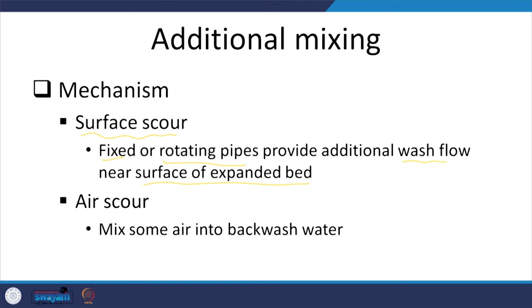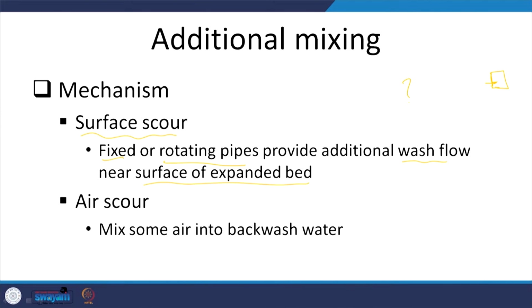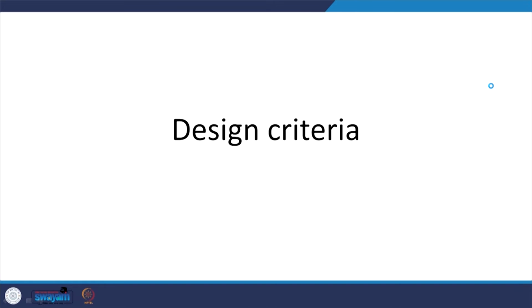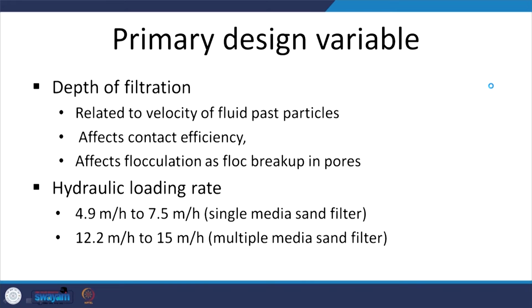Yes. Again, where is this backwash water going to come from? So you will typically store some treated water to be used for backwash. That also will have to be taken into account when you are going to design a particular filter, right? The amount of backwash required and how frequently it is required. So design criteria, obviously.